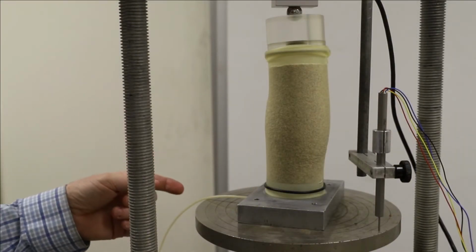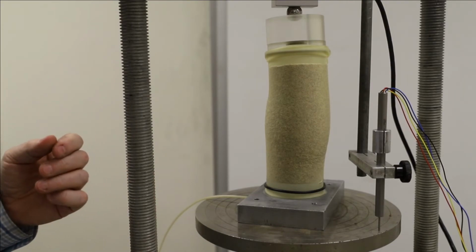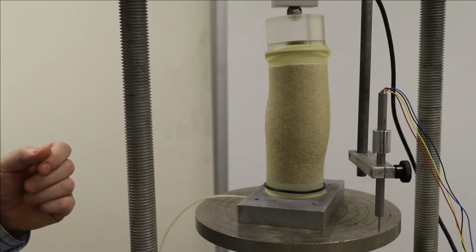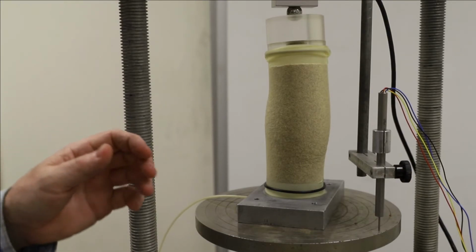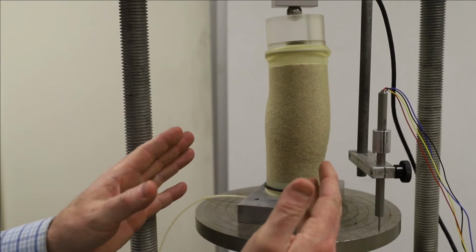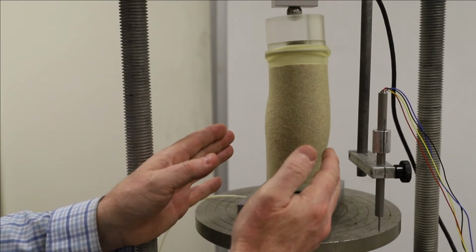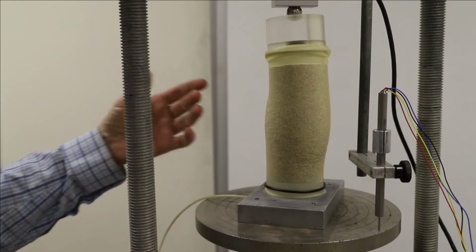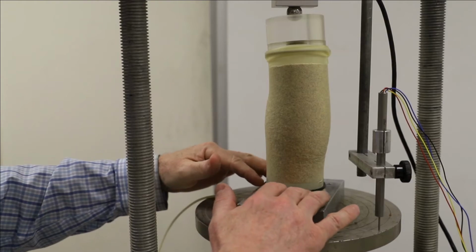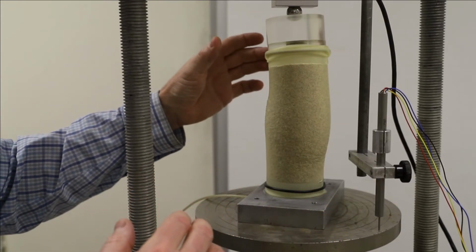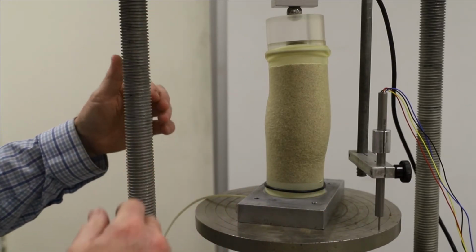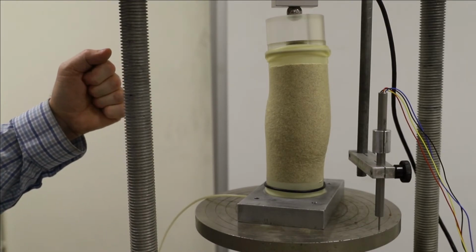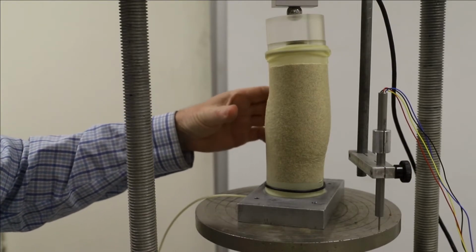So now we're beyond 10% strain, which is quite a large strain. Triaxial assumptions about triaxial tests start to break down at large strains. As you can see, even though this bulging is continuing through the center part of the sample, it's not really happening right at the caps, at the top cap or the bottom cap. That's because those zones are sort of protected. Again, they have a rigid cap right adjacent to them, so shear planes can't pass through them. So the bulging is confined mostly to the center.